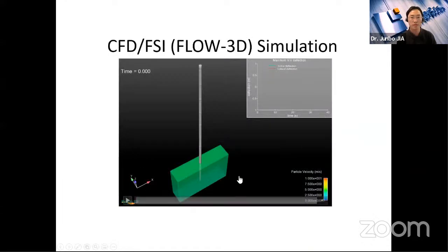So this is one of the, if you still remember, I introduced some vortex-induced vibration resonance problems. With experiments you can do some numbers, but the essential thing is you try to use experimental data to validate your computational model so that in the future design, you can heavily rely on your computational model. That's the way we use it for our daily engineering design.